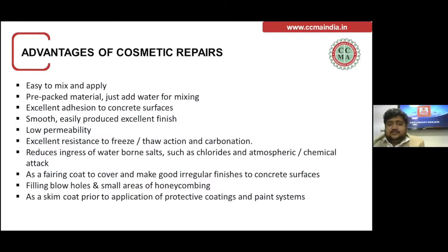So the advantages of cosmetic repairs. It's easy to mix and apply. It comes in a powder form. You just need to add water. It's pre-packed, so no labor-oriented mixing is required. It's just water to be mixed in the right proportion. Excellent adhesion to the concrete. It will not come out very easily. Smooth, easy application, and the product finish is very good.